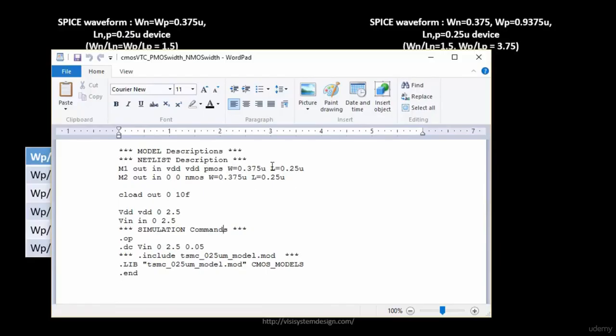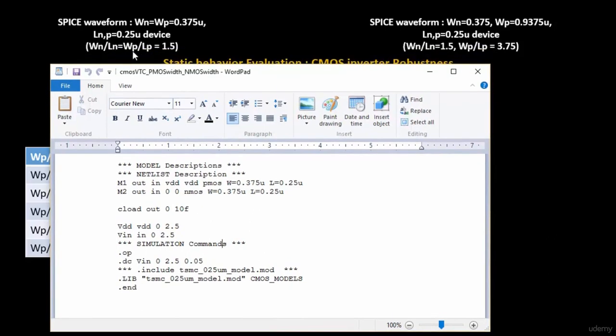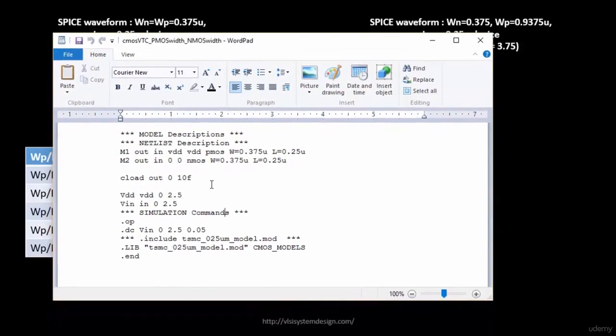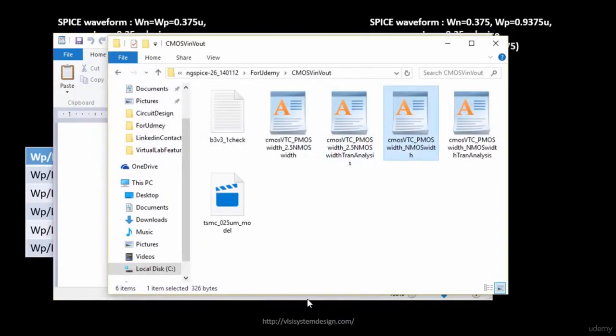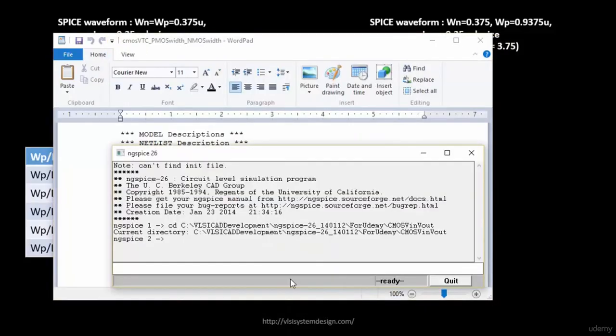While deriving this waveform, we had looked into each and every point of it, at what regions of operation your PMOS and NMOS are in. In this case, we identified that your PMOS and NMOS are in saturation region. It means that they are kind of turned on in this area.